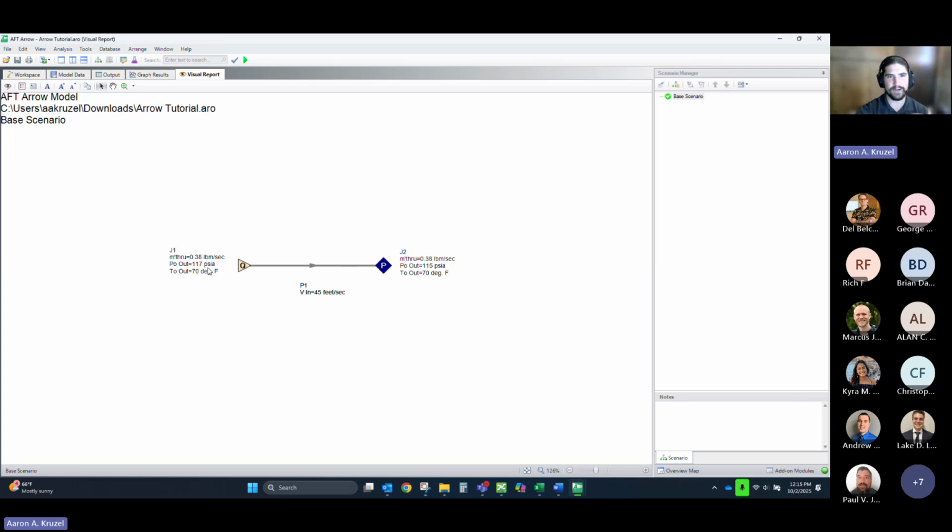So you can see now to account for the 115 psi A that we're getting at the end, we have to up our input pressure, and now it's showing 117. So what does that mean? Let's say your compressor is running and you are putting out 100 psi or 102 psi now, you're dropping down that 2 psi. Let's say there was more tumultuous of a path. That's going to drop it down another 5 psi, 10 psi, and then theoretically, if there's a lower limit to what the end user can receive, then you start losing efficiency. You might even lose function of the equipment. So accounting for that pressure loss is very important.